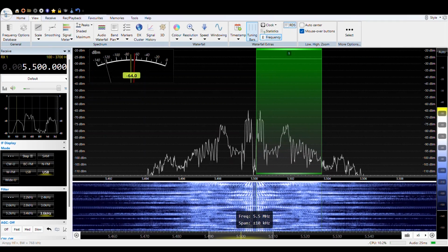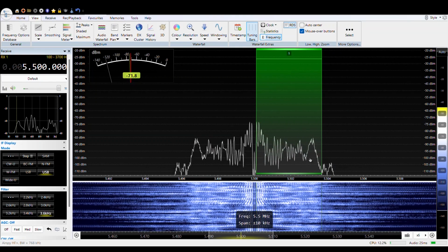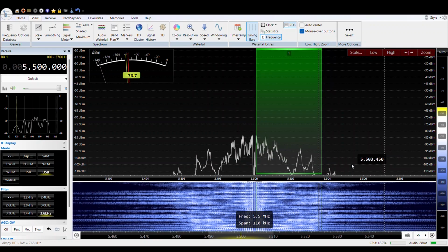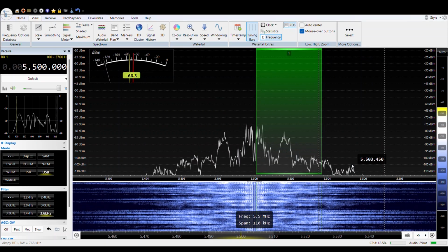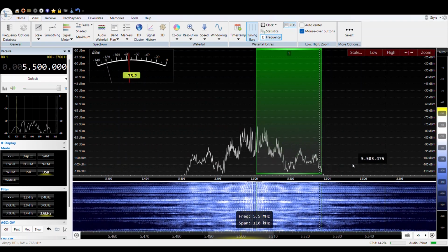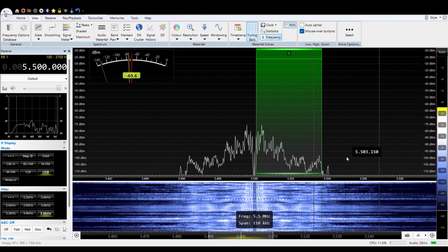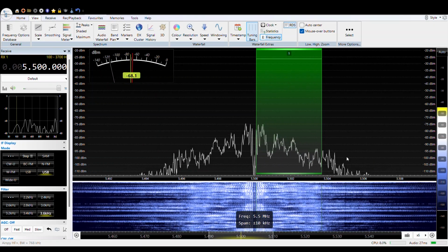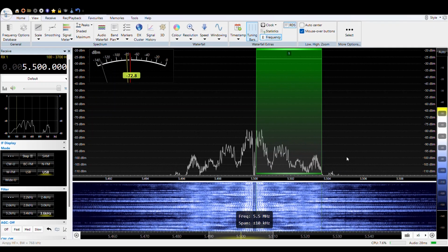So, in theory, even though I could put this on the air right now and communicate, it's just way too weak. And, of course, there's all this extra spectrum garbage here that would create all kinds of interference. So, don't want to have that out on the air. And that's what that filter will help do. And then, of course, the IF amp and the rest of those stages, including the second mixer, are going to boost it to the final transmitted frequency.